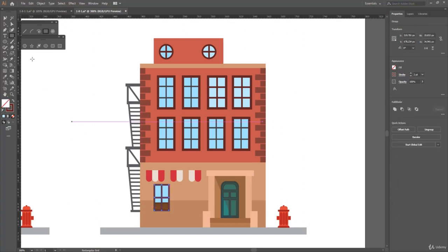Now I come over to the tools panel, and I click on the direct selection tool to select it. Then I return to the window I have created, and I select the horizontal divider. I click away to deselect the rest of the rectangle. I drag down the selected line like that. Then I select the selection tool, and I come back to the window I have created to move it. So I click on it to select it. Then I click and drag to the right.